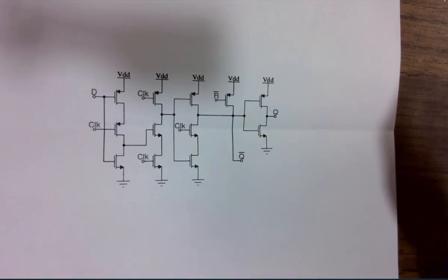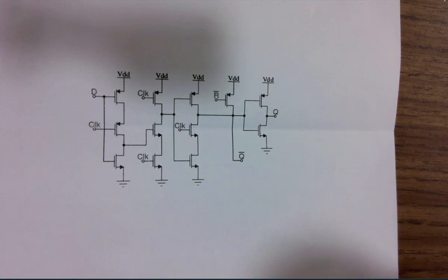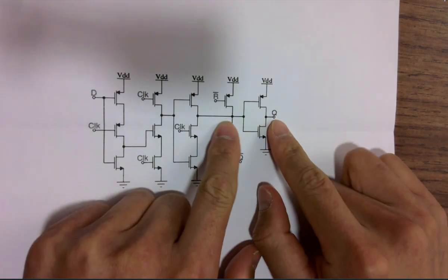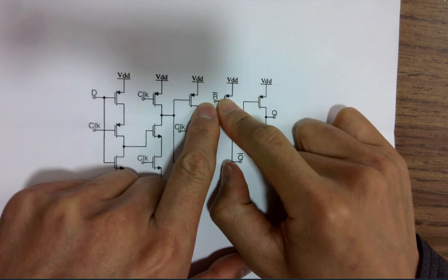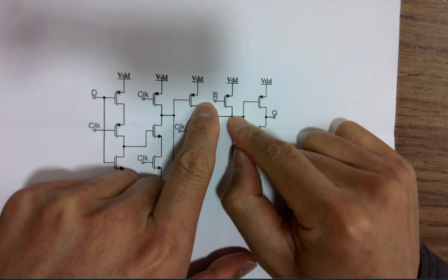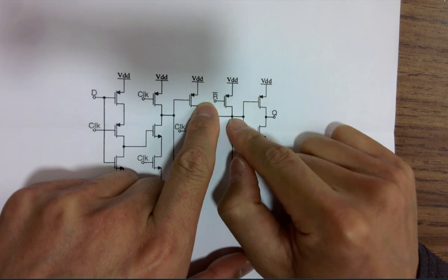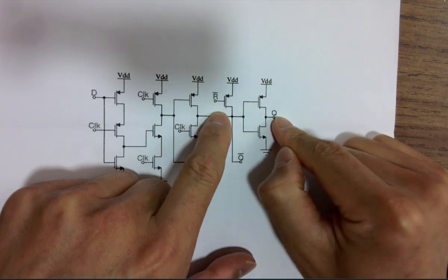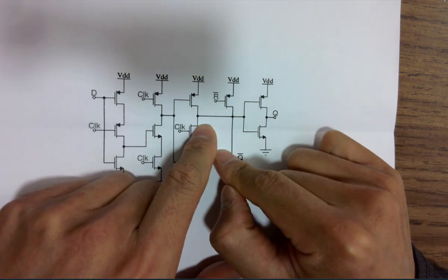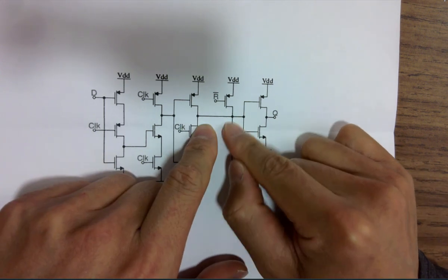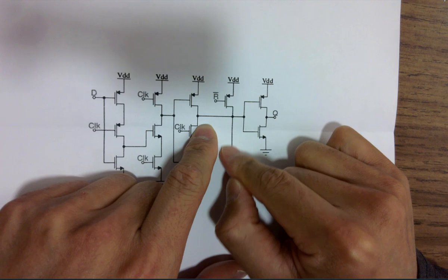Well, I guess that's my question. If it doesn't have a set, then how is it? Yeah, you can add a set. See? So the thing is, you see this is the final stage inverter, right? So when you reset it's active 0, you put 0 here, this point is being pulled up, right? So you're getting a 1 here, 1 getting inverted, getting a 0. So that's how you're resetting it, right? If you're setting it, you just add an NMOS at the bottom. Oh, you just simplified it. Yeah, just add an NMOS at the bottom.